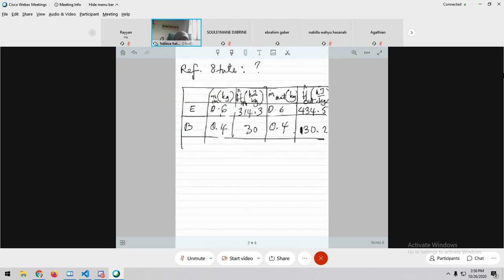Now, what system are we looking at? Anybody? Open system. So do your energy balance for an open system: kinetic energy, potential energy, equals your heat flow rate and your shaft work. Because we are dealing with a heat exchanger, there are no parts turning inside your system. There's no kinetic or potential energy. It's already stated in the problem that you can ignore kinetic and potential energy. So your heat coming in equals the change in enthalpy.